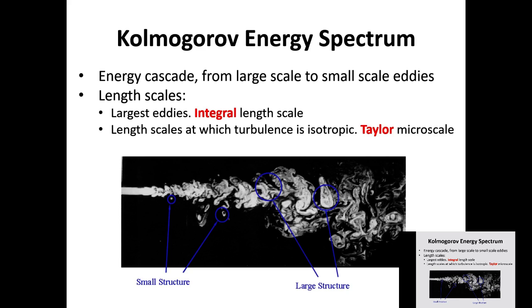And then when you look at these eddies, you determine a grid size and say that some of the eddies which are smaller than the grid size will be discarded in your turbulent calculation. Yes, they have to be, because the grid doesn't see the eddies.